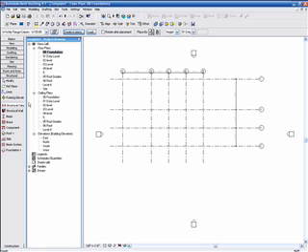Now the type we're looking for is already pre-selected for us. I'm going to go to the options bar, which is right in here. Select height. Okay. And we're going to say go to the roof. Go to the roof garden. Okay, so in the event that something changes height-wise, these columns are going to know I go exactly to the roof no matter what.